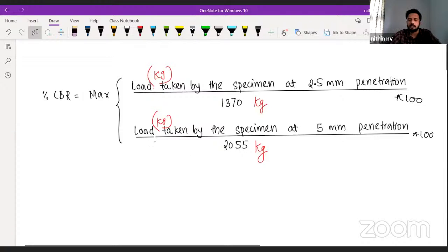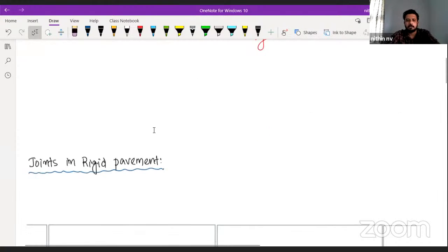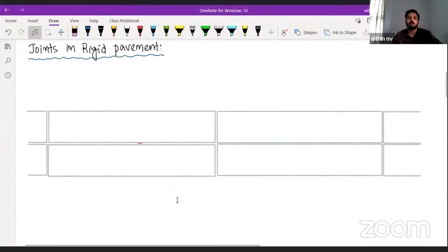Yes. Now see, in pavement design, I'm just telling some extra points, not that complicated. You can self-study also. The rigid pavement we are actually making as a combination of some slabs. So the gap between two slabs, we call it expansion joints. These expansion joints we give to take care of the expansion of the slab. Very easy things, you can study on your own also.